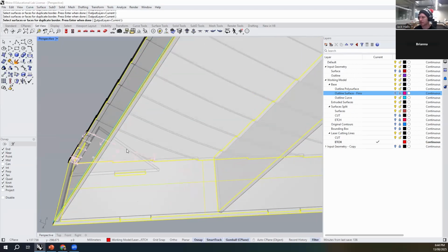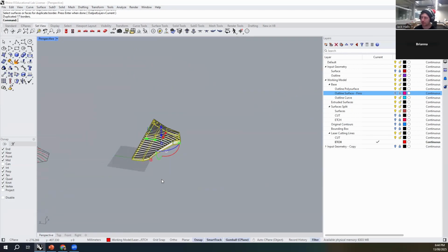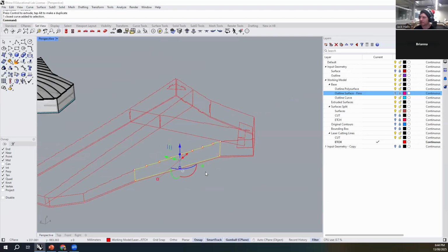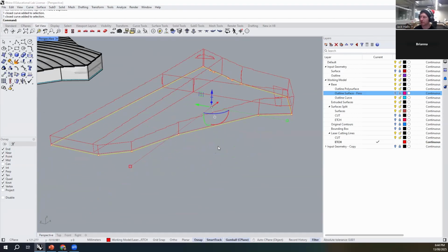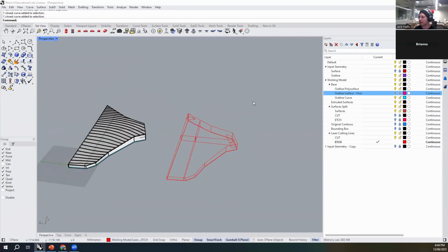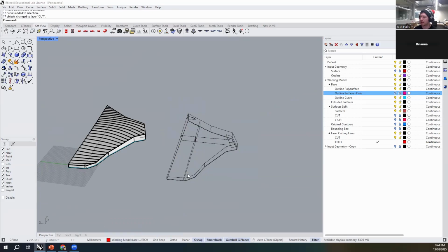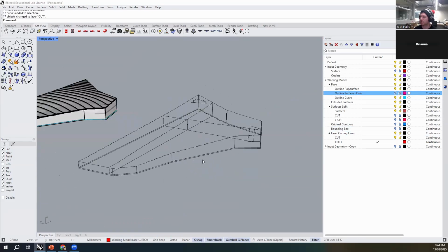This space. And go. So those are all the things that we want to cut. We bring those out, we enter, we can see it's basically a whole bunch of individual curves. Some of them are quite easy and ready to go. These are all cuts, I should say. So we can select that geometry and just move it straight to our cut layer for our laser cutting lines.